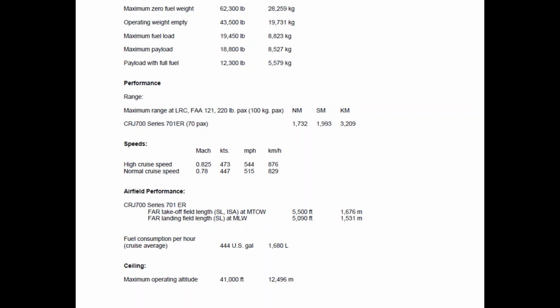As we already discussed when talking about ISA, regardless of where you're at, conditions are rarely just ISA. Occasionally you'll come across something like, wow, we're at ISA here, it's perfect. But normally we're never at ISA. It's always going to be colder, warmer, the elevation will be higher, you're not right at sea level. When we get into performance, you're going to see how those really do change. At a higher elevation airport with a really hot temperature, the required field length to take off in some cases can jump all the way up to 9,000 feet, nearly doubling the length you would normally need at standard ISA temperatures and sea level. But this is just giving us that generic thing to go off of.